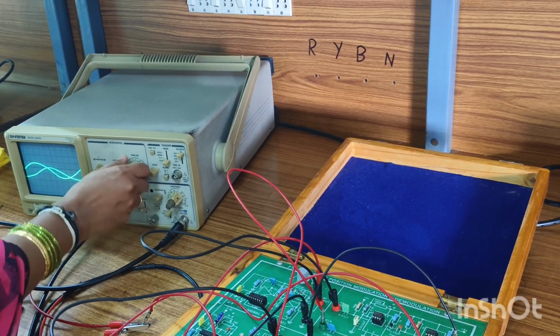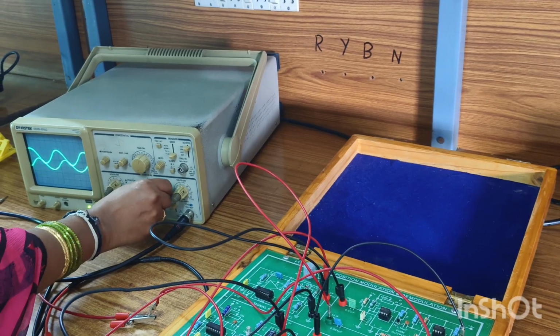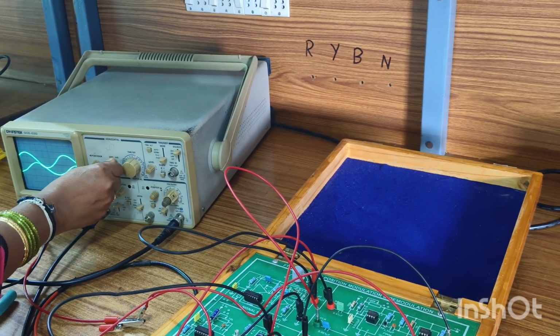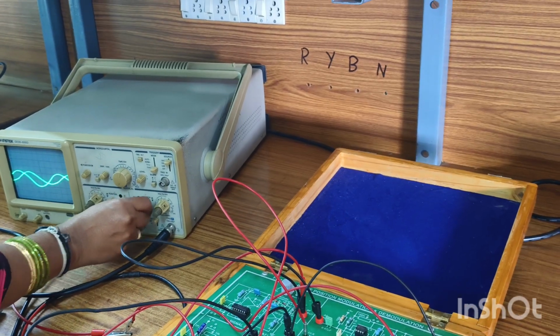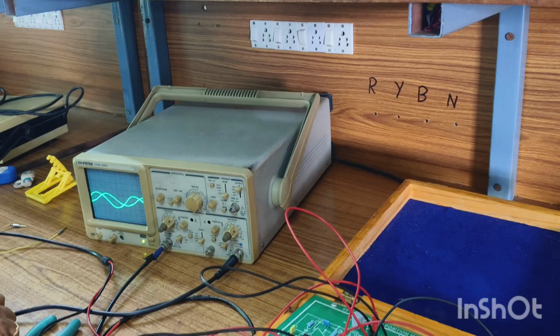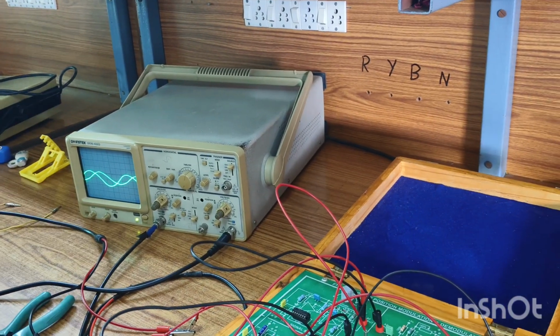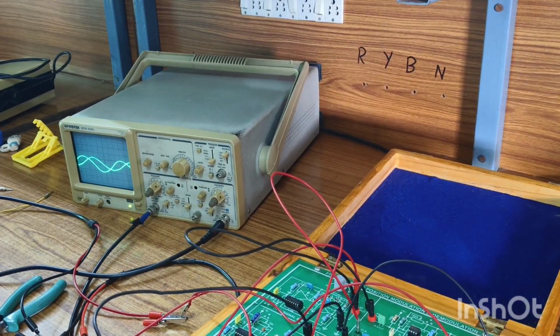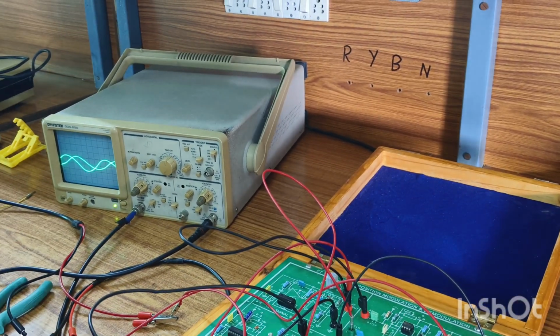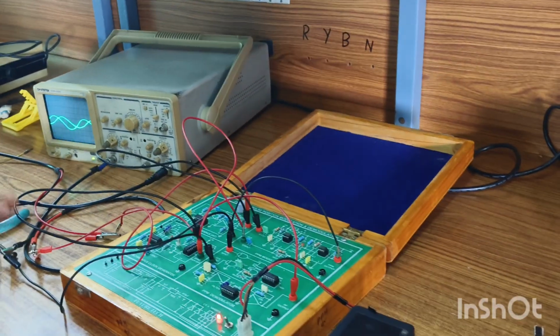See here, we are going to get a phase difference always. Okay, nothing to worry about that phase difference. Whenever you have the positive and negative, this phase difference we can have at the demodulation. We can neglect that, but try to check whether the amplitude level and time period are constant or not. That we need to check. This is about the pulse position modulation and demodulation.